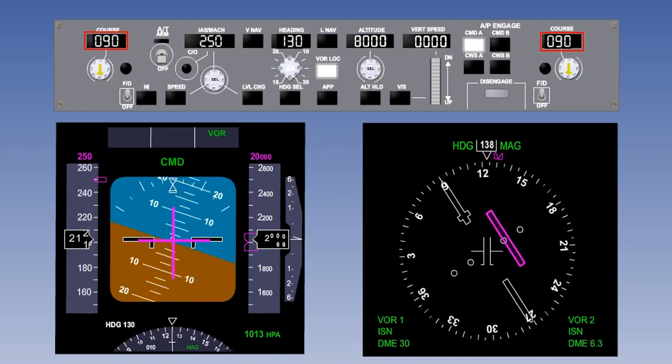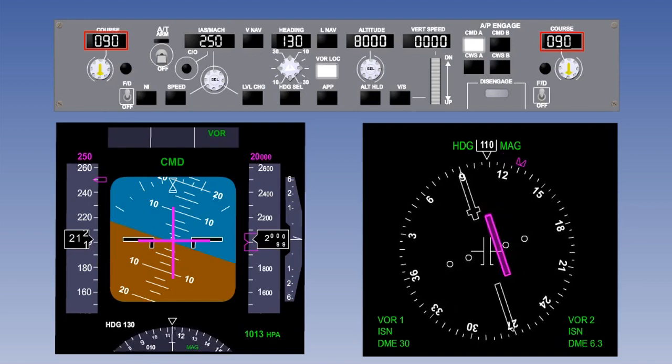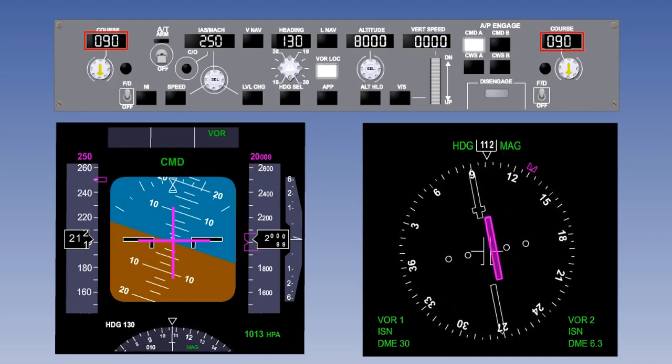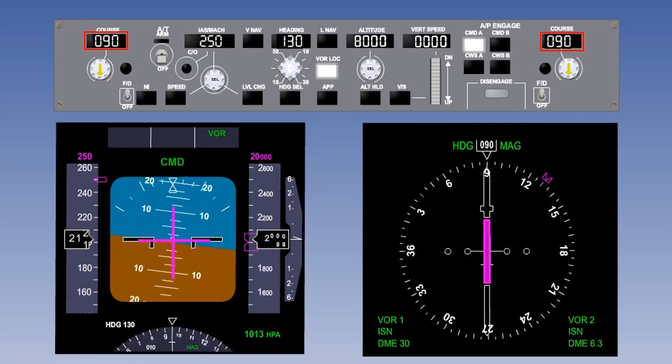The aircraft will be rolled back wings level to maintain the magnetic course at the beacon, the roll channel of the autopilot being controlled by deviation signals from the radial. The heading selector takes no further part, but will be positioned by the pilot to the current heading when the aircraft is established on course.